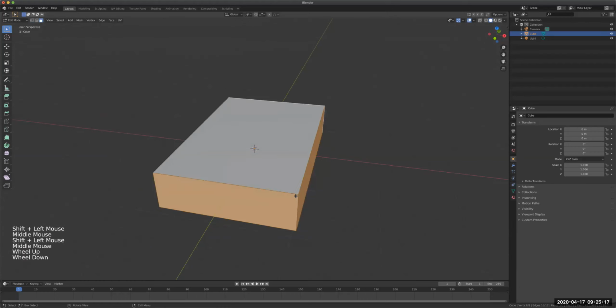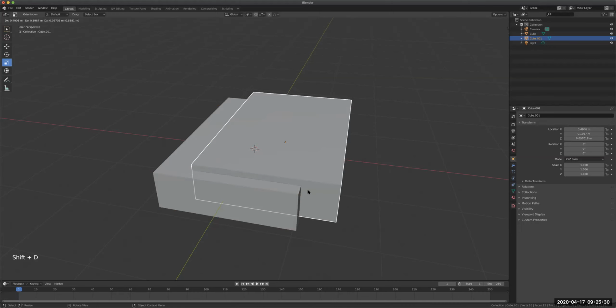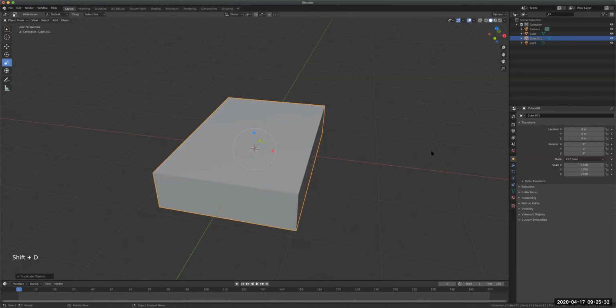Okay. But it would be a good idea right now, before I destroy this, to duplicate this and hide it. This is our page, okay? So I'm going to duplicate this one, Shift D to duplicate. All right, and then I'm going to right click to cancel the movement. Go right here, and I'm going to put pages right here. So that'll be our pages, and I'm going to hide it using the visibility icon. Rename the original cube, so this will be the cover. All right, so at least we know what's happening.